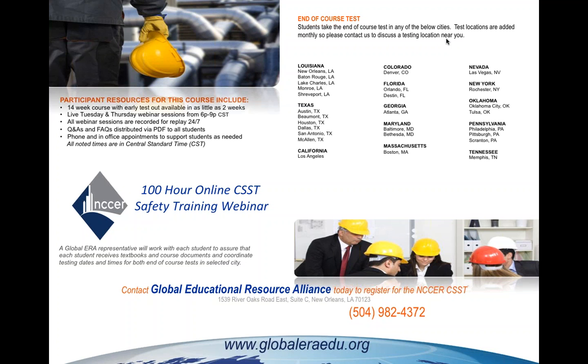In addition to that, keep clear of power lines like we talked about, a minimum of 10 feet away, sometimes even 20 if it's over 50,000 volts or we're not certain. Make sure that we talk to the utility companies to find out where all overhead and underground power utilities are located. Make sure there are no caverns, coffer dams, vaults, or anything else underneath where we're going to be operating a crane. Assure those ground conditions, and then learn the crane signals, especially the emergency stop signal.